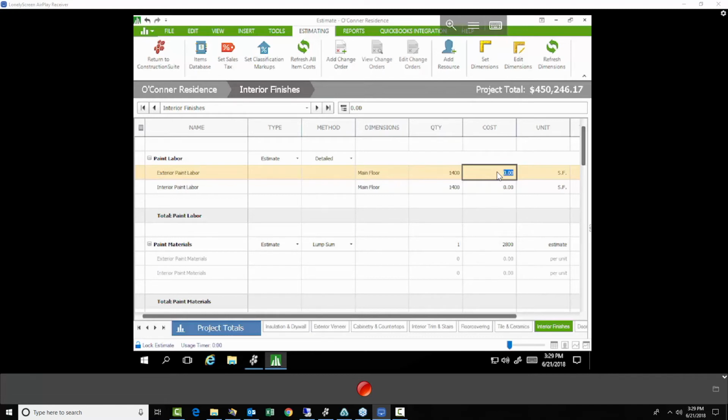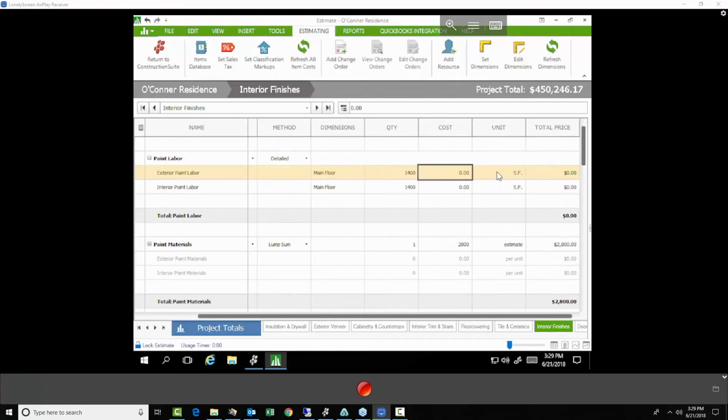Now this is also really applicable for things like main floor or total covered area when you're talking about total carpeted area, because that'll help calculate quantities for cleanup and for the carpet itself and for the pad or the underlayment and install labor and all these different areas. Again, surface area for interior walls comes into play when you start talking about hanging sheetrock, or the perimeter itself would be for baseboards or crown molding if you're going to be doing that on jobs. Even with office spaces like ours, almost the entire office is carpeted in the same way, so the total square footage for the office becomes a very applicable dimension set, because that's going to help come up with a rough carpeted price.